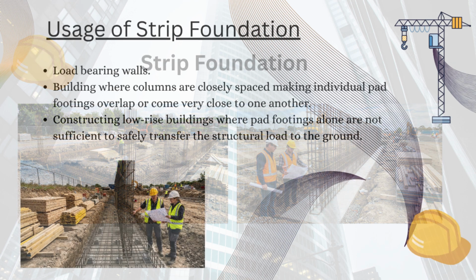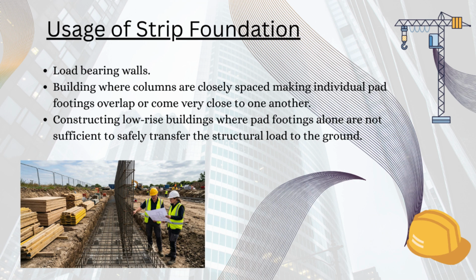So when do we use a strip foundation? Load-bearing wall needs to be constructed. Columns are closely spaced, making individual pad footings overlap or come very close to one another. Constructing low-rise buildings, where pad footings alone are not sufficient to safely transfer the structural load to the ground.